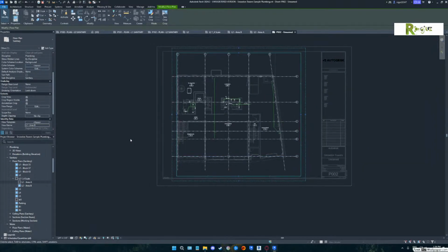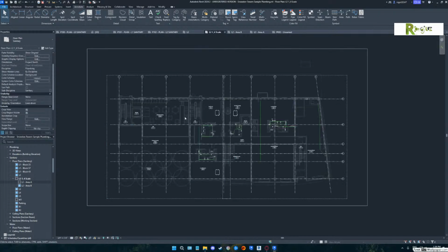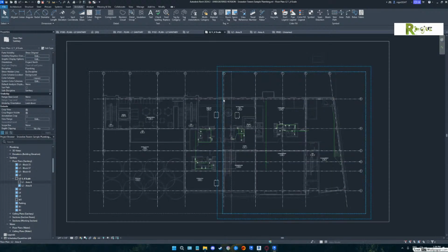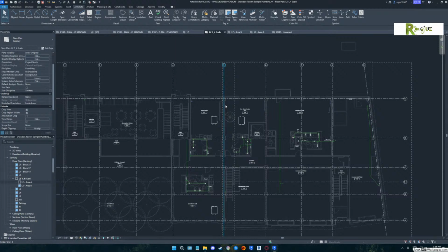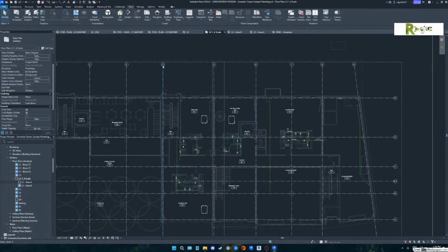Now, what I was going to show you is on the parent view. That's the parent view. The only thing we like to do on top of where the overlap is happening of those two views, we like to draw what's called the match line. And that's a special creature that's under the view tab, I believe. You would think it's annotate, but I'm pretty sure it's view. Yep. It's under sheet composition. There's a thing called a match line. Match line. Yeah, I see it.